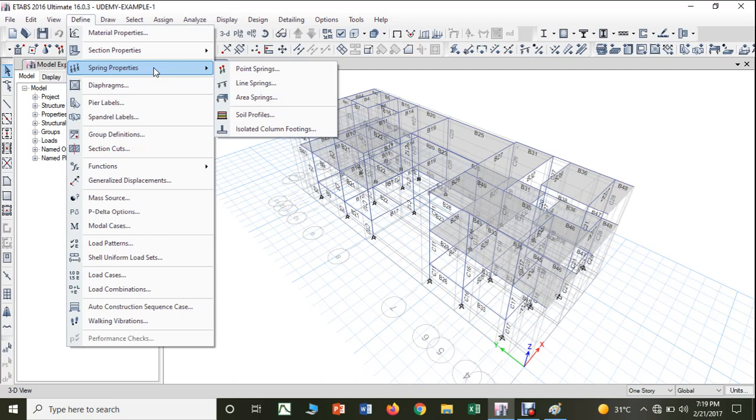We assume that the soil behaves in its own way separately, and the building behaves in its own way separately. By assuming that, without considering anything about the soil properties or its nature, we consider only the building, analyze it ideally and design it. For normal kinds of problems, for very simple buildings, it is sufficient.